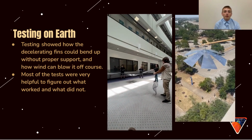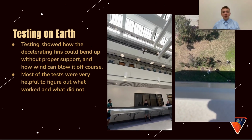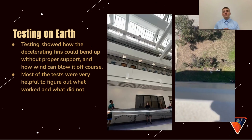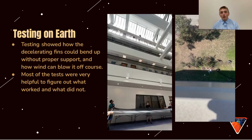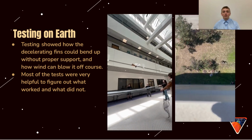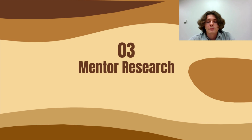We went through a total of 3 tests. The first was just for the fins alone to ensure they worked how we envisioned. Next, we attached our hardware and the lander's stand-in. This test ended up failing due to the lack of supports to prevent our fins from bending 180 degrees. We went back and reinforced the top with rigid dowels to prevent our fins from flipping back. This resulted in our final successful test.